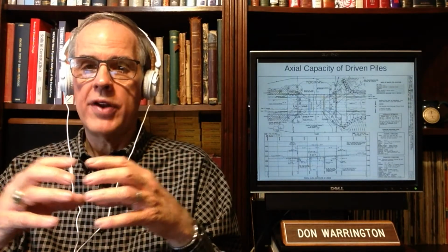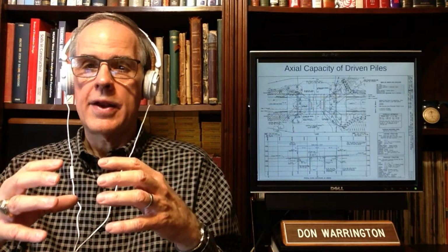In the process of being driven into the wood, the nail actually compresses the wood around it. And that compression, that radial compression, becomes axial compression, and that basically helps hold the nail in place through friction along the surface of the nail. You get the same thing with driven piles.